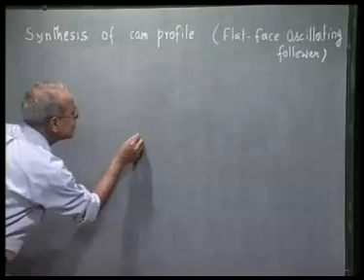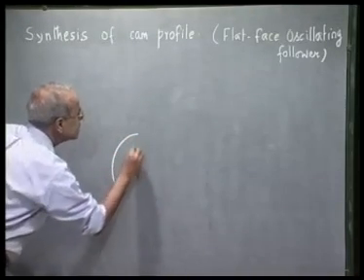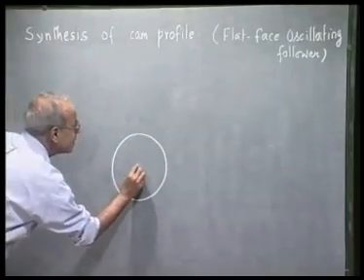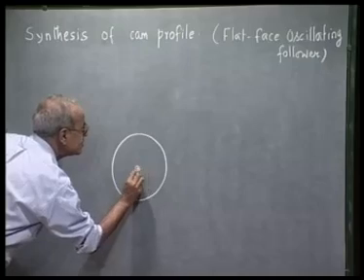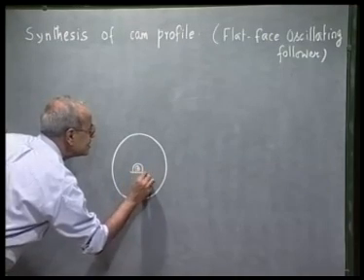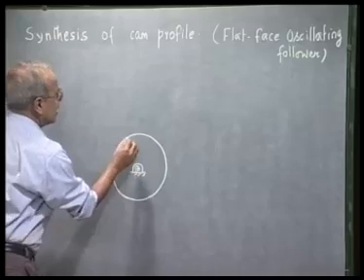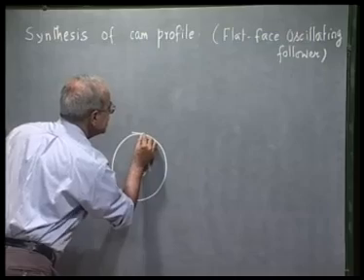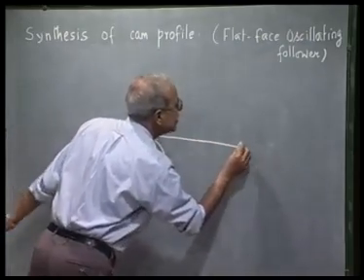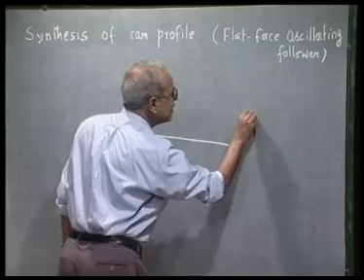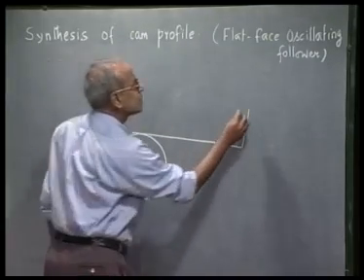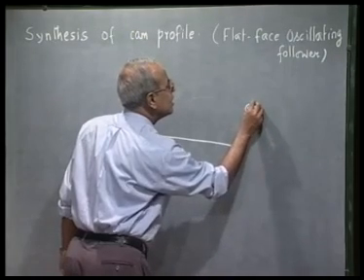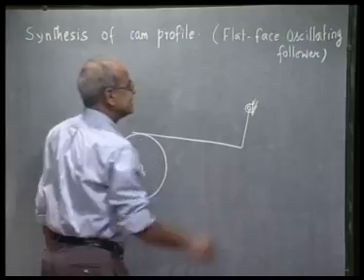Let the base circle of the cam be given, and when the follower, flat face follower, is in contact with the base circle, that is the lowest position of the follower, and the oscillating follower is hinged at this location.